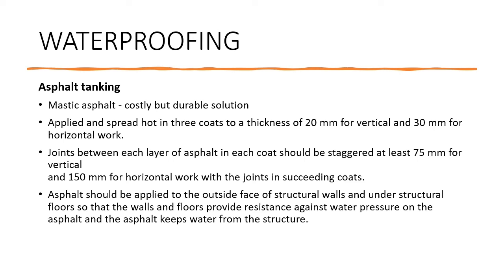Asphalt should be applied to the outside face of structural walls and under structural floor so that the walls and floor provide resistance against water pressure on the asphalt and the asphalt keeps water from the basement.